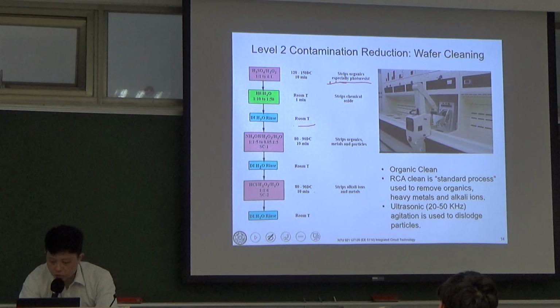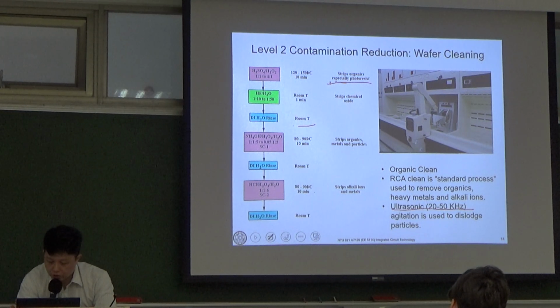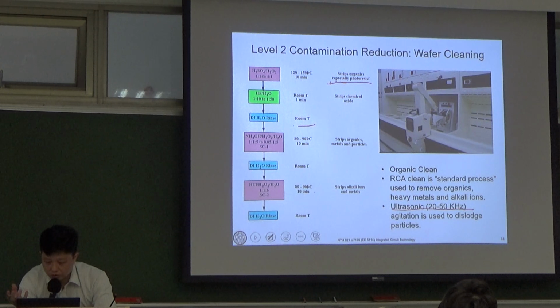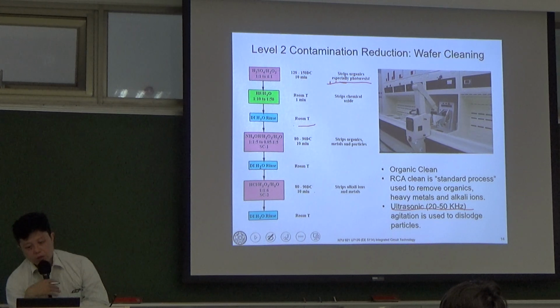And sometimes you will use ultrasonic to help you, because this agitation can help you to dislodge these particles. Okay. But you have to be careful. This ultrasonic, sometimes you break your wafers. But silicon is more robust. For some compound wafers, then you have to be very careful.